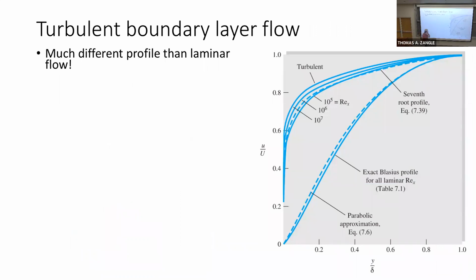But to use what we know about turbulence, we need to know a velocity profile. Remember, if we came back to our discussion of coefficient of drag, we said that we wanted to approximate the velocity profile in order to solve for coefficient of drag on a flat plate with a turbulent boundary layer. The Blasius solution gives us the velocity profile on a laminar boundary layer, but we need something for the turbulent boundary layer as well.